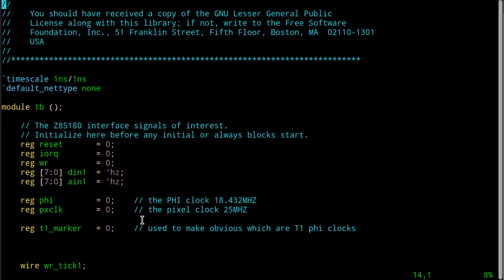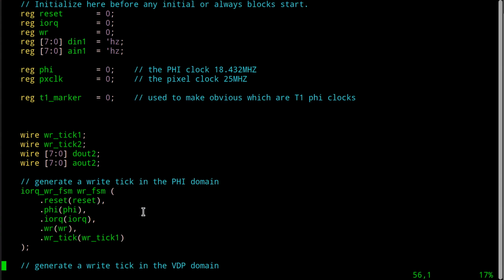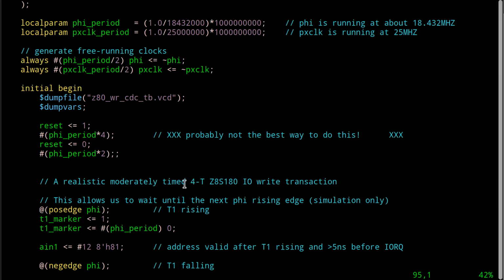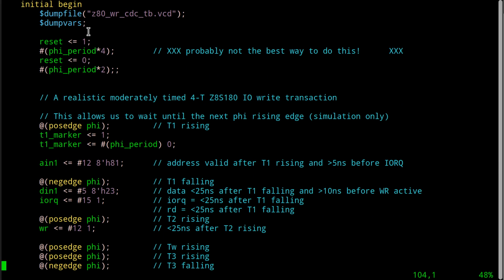But an ASIC will start up in a very random state because it just powers on out of nowhere in raw silicon, where an FPGA has a program file that comes in and all the D latches and things like that are programmable inside your startup boot file, and will always start up in a consistent way when your FPGA resets. So if you're designing to build an ASIC, you definitely want to have a reset to reset all your stuff. Anyway, okay, so that aside, I think I beat that point repeatedly on my other FPGA videos.